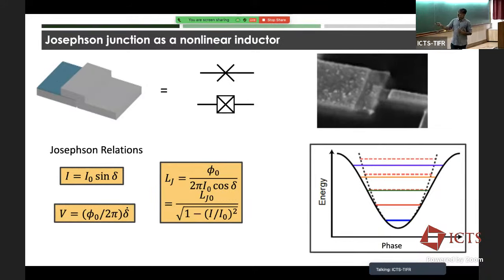But this is sort of the origin of the nonlinearity. You can work with these in terms of equations of motion, or you can work with these in terms of an expansion of the inductance as a power series in current. So that's what gives rise to the nonlinearity. And then it's just an inductor, you put a capacitor, you get an LC oscillator, and you get your transmon qubit or other kinds of nonlinear oscillators you can build using these systems.